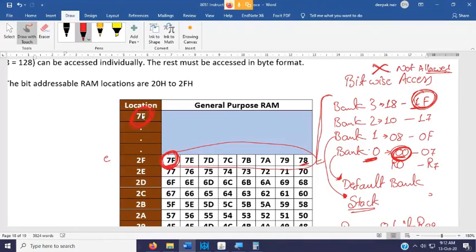These two are two different 7F. What does that mean? This 7F is the location within 2F, which is bit addressable, and some instructions can access this particular 7F by using bit addressable commands. Whereas this 7F is the register itself. Here this 7F is within 2F, whereas 7F has its own 8-bit register. So remember that